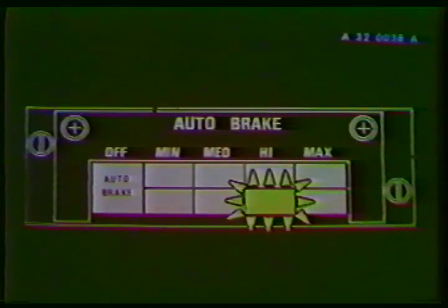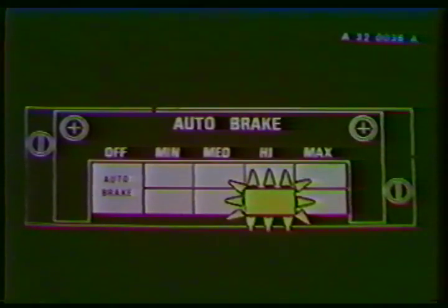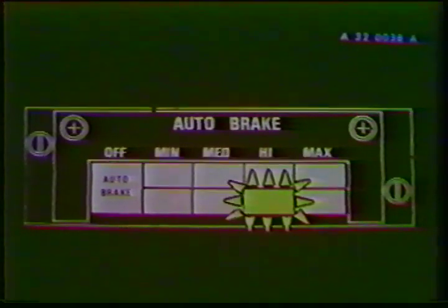After touchdown, as soon as the ground spoilers extend, braking is automatically applied as long as the aircraft is rolling. When the aircraft deceleration rate reaches the one selected, the white light extinguishes and the lower part of the push button illuminates green. Braking action is automatically canceled when the spoilers are retracted. The white light will come on again, indicating that the mode is still engaged.